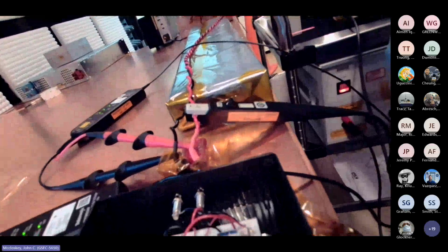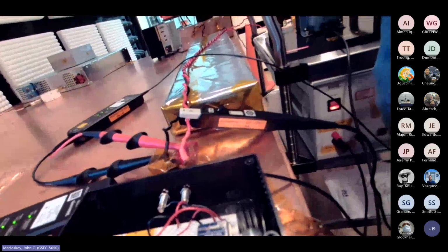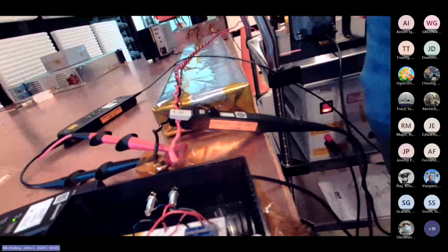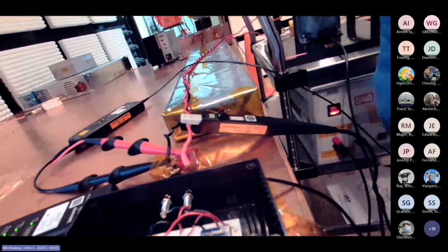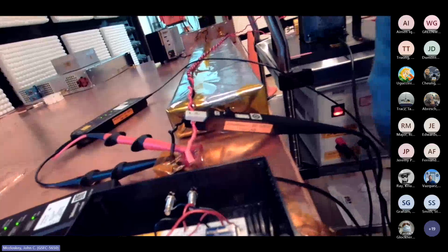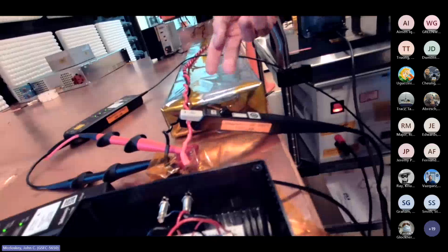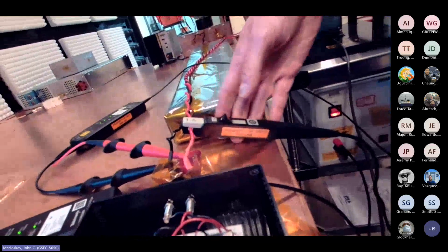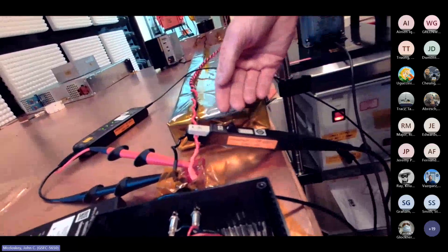And the important thing there is, because I've had this discussion with people, isn't 1 volt into half an ohm 2 amps? Well, yes, it is, but it's the open circuit voltage of 2 volts that you need across the half ohm source impedance to get you the 1 volt into your half ohm load. So the 4 amps comes from 2 amps to 2 volts of open circuit potential across the half ohm source impedance.